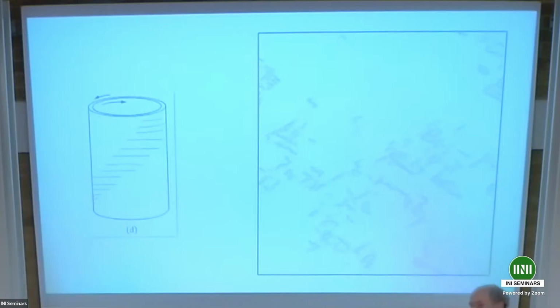And it does it by taking into account the interaction with the mean shear. I might come back and say a little bit about what that mechanism is, depending on how the time goes. But it was purely phenomenological. It didn't come from the Navier-Stokes equations.